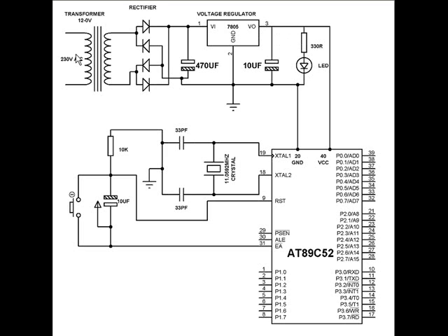If it is to be operated directly from a battery, we do not need the supply, as the microcontroller needs 5 volt. What we do, we take a 6 volt battery and connect a diode in series, which solves the purpose of supplying 5 volt to the microcontroller's pin 40, and pin 20 is always negative. The other connections are very standard.